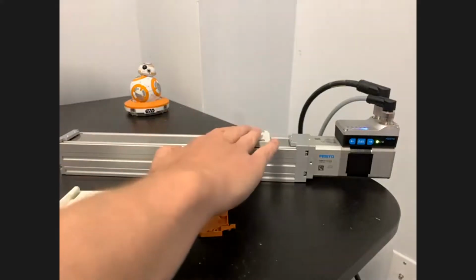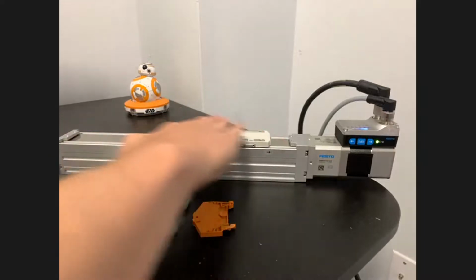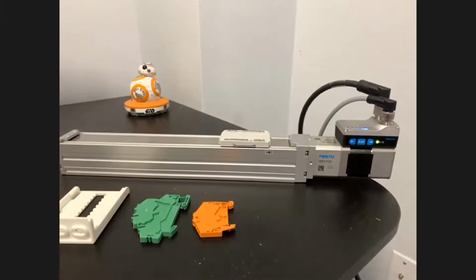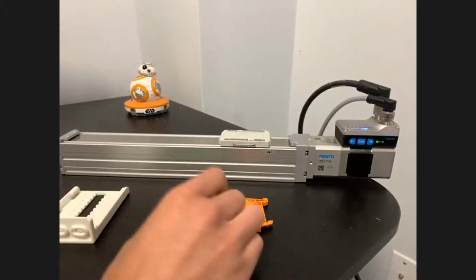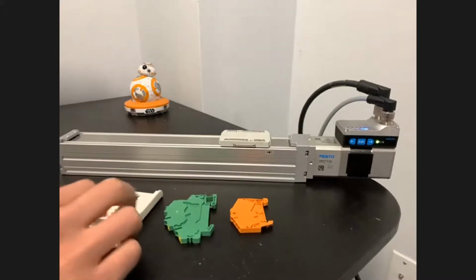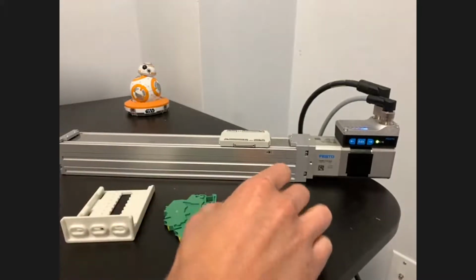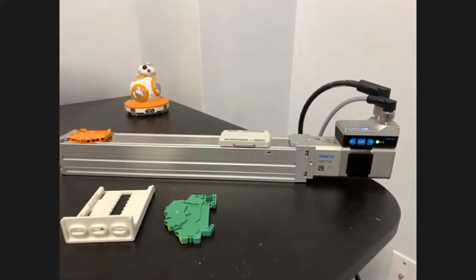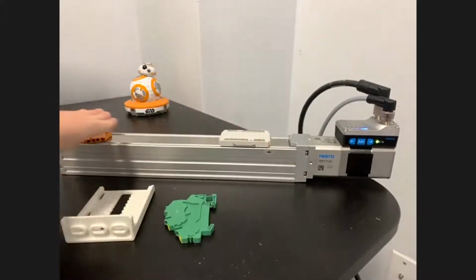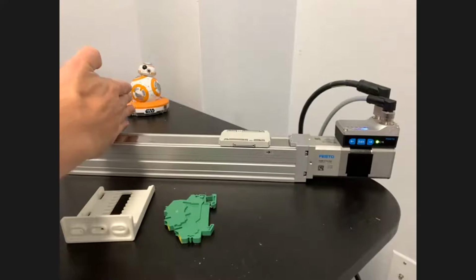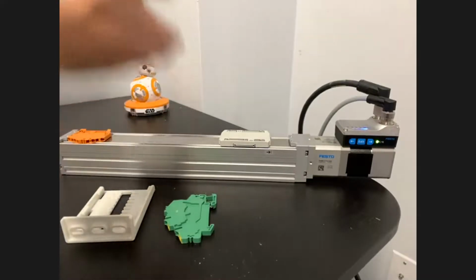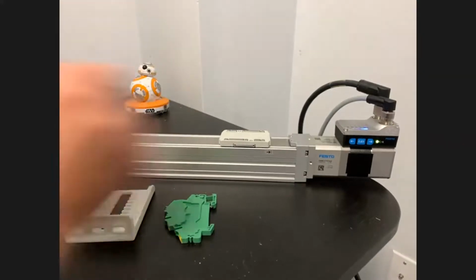So this carriage here slides back and forth. I have my 3 parts here, and I'll measure them. I'm just going to place the part in front of the carriage, and the carriage is going to extend, and then it's going to hit the part. And then that's going to trigger a done bit, which is going to tell the PLC to pull the...